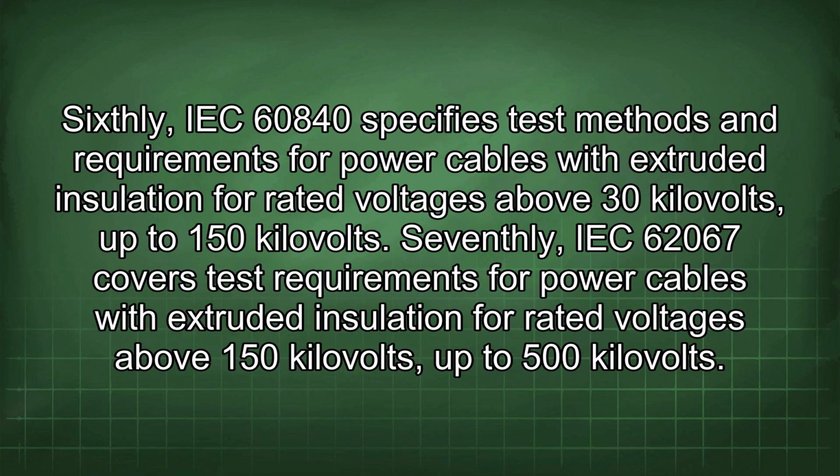Sixthly, IEC 60840 specifies test methods and requirements for power cables with extruded insulation for rated voltages above 30 kV, up to 150 kV. Seventhly, IEC 62067 covers test requirements for power cables with extruded insulation for rated voltages above 150 kV, up to 500 kV.